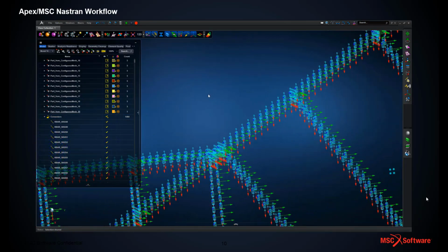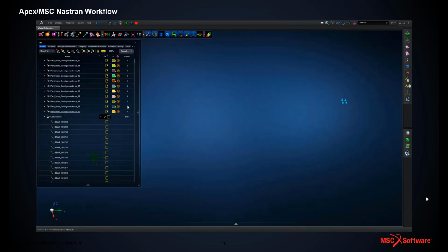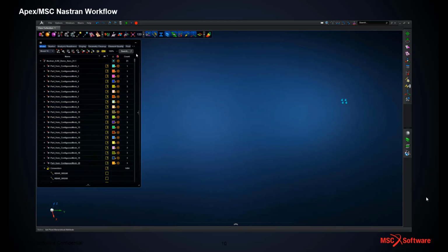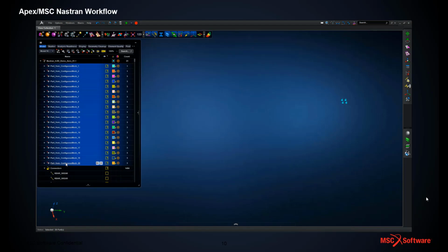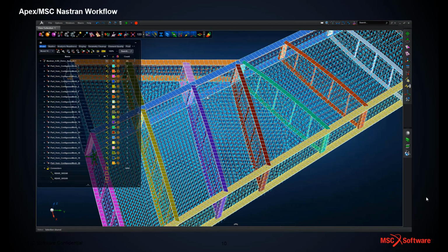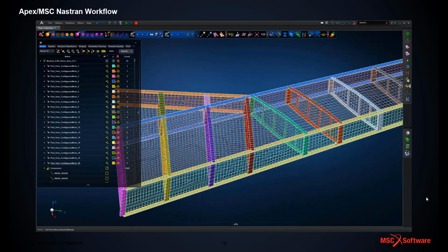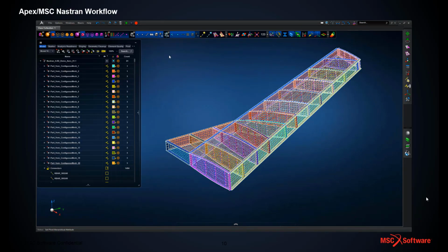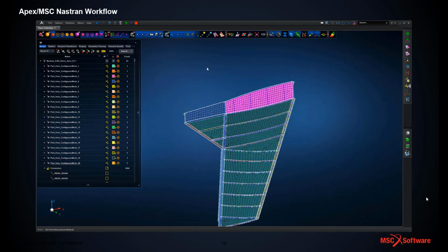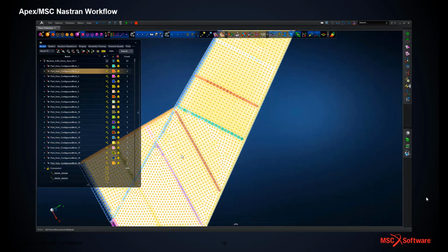So we can see here we've got a local coordinate frame defined. Again, because these are zero length, they're all aligned with the global system. Looking at each of the parts, we can just show only the regions of interest, or the region we want to look at. So again, this is a typical wing box model from a typical airframe supplier. If we go into render mode, we can see the wing skins upper and lower, the spars, the rib layout, the trailing edge definition, what have you.